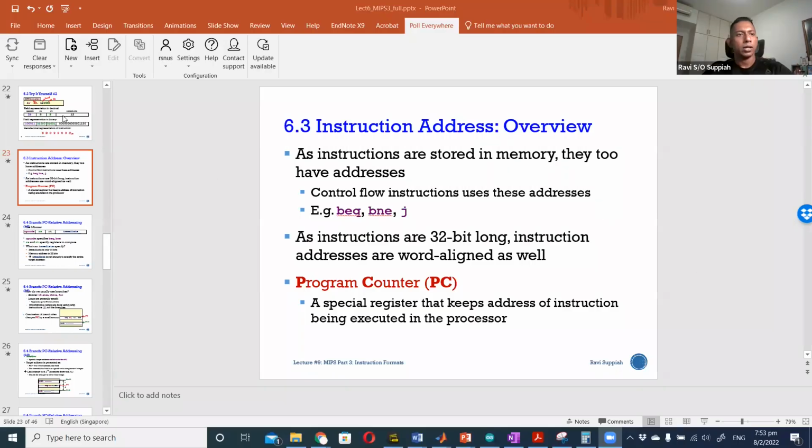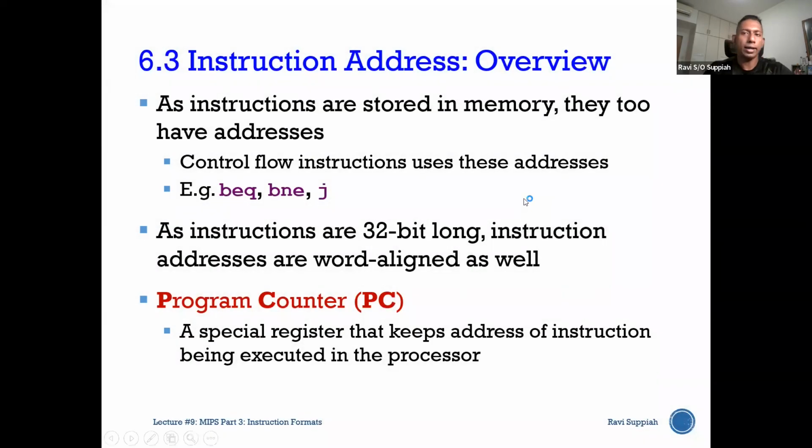Resume back. Okay, so there's a question: if the immediate value is negative, we need to use 2's complement. Yeah, so basically MIPS uses the 2's complement system, and any negative number has to use 2's complement as its representation form. Right now we are at the I-type instructions. We saw the load word just now. Now let's look at another type of I-type instructions, which are the branch instructions.